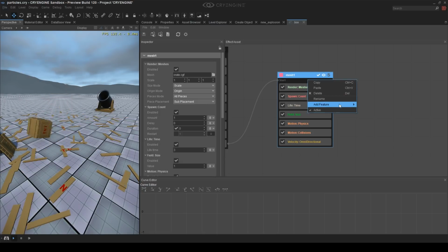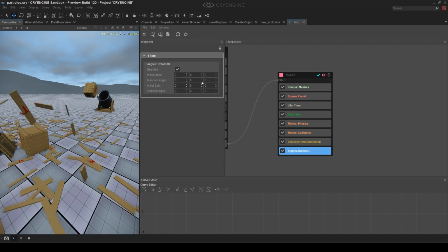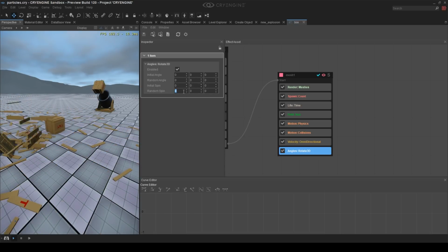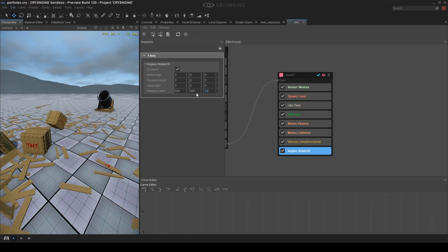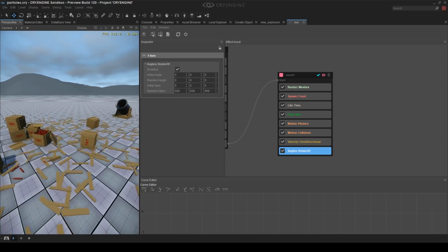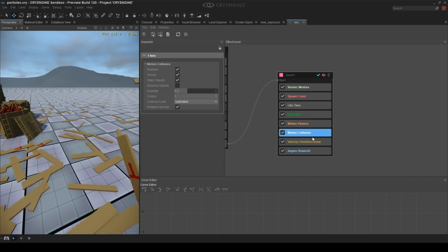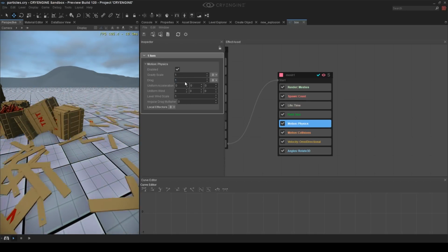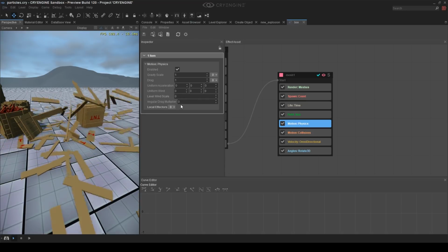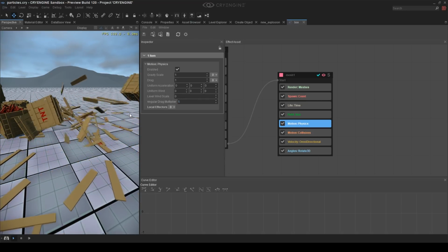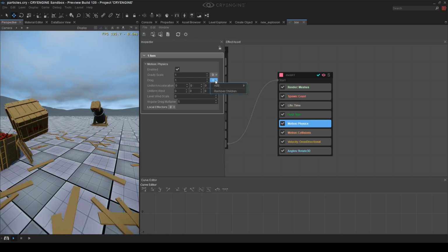And what we also want is we want them to rotate, and since they are 3-dimensional, we need rotate 3D, and we don't want random angles at the beginning because they should be on this exact point where the box is. They should spawn on the same spot, but we could have just like 500 on random spin, so they would start spinning. But now you see at the moment the friction does not affect the spin, so we're just gonna fix that, or like hack that, by giving them some drag. In the drag there's how much influence you want from the level. I set it to 0, but I want the drag to be a multiplier on the rotational thing. But now you see they stop rotating way too quick.